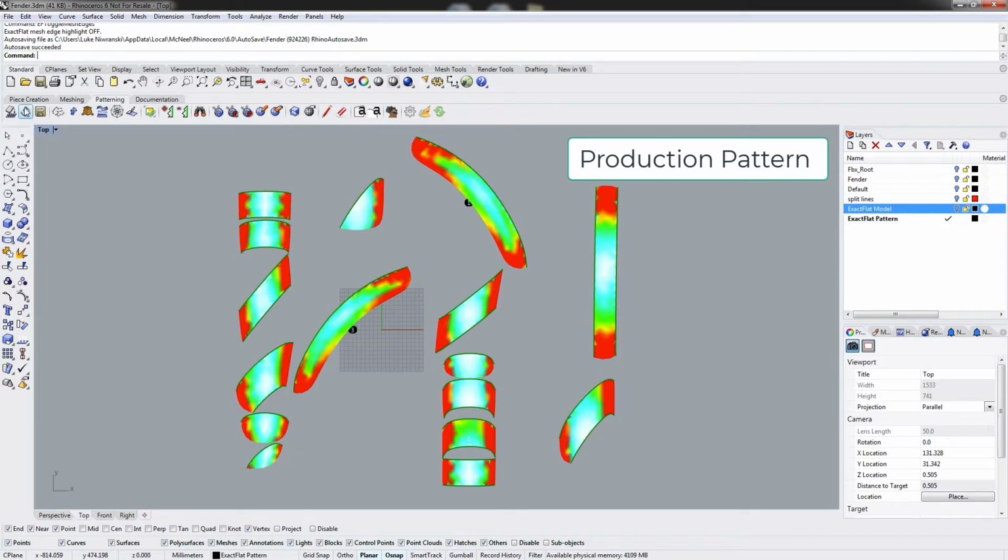And it does that using the mechanical properties of the material. So whether you're using a cotton or for composites, a fiberglass or carbon fiber, some kind of weave, each material is going to have different mechanical properties, and ExactFlat simulates those mechanical properties during the flattening process using the spring tool. So first stage flattener is very fast, produces unoptimized flat patterns. Our second stage flattener, the spring, it takes a little bit longer to run, but it relaxes your patterns to production quality.